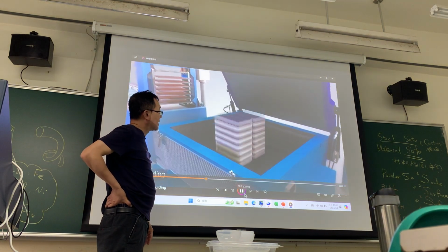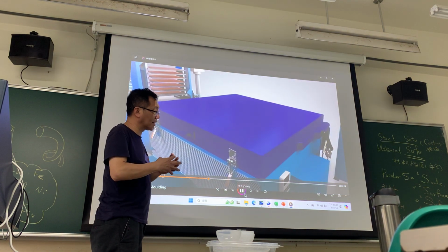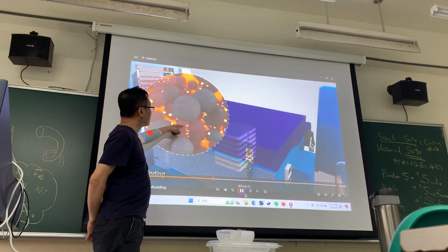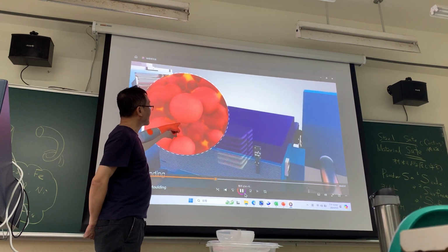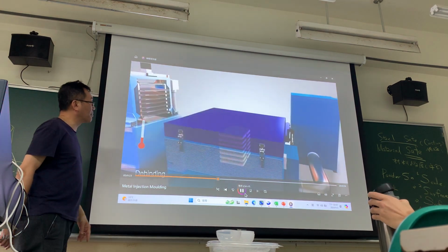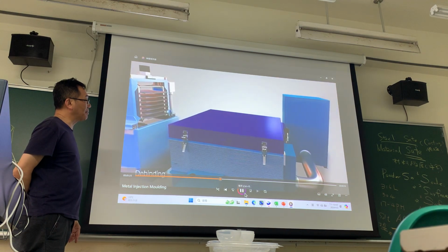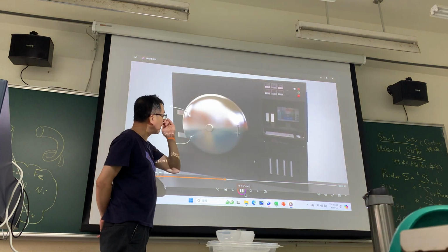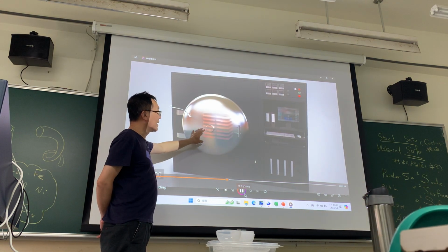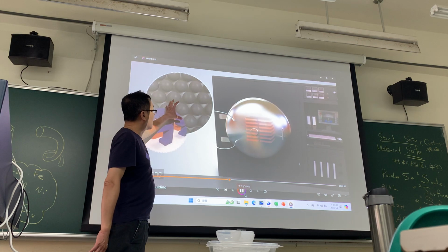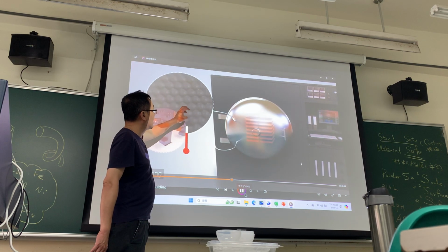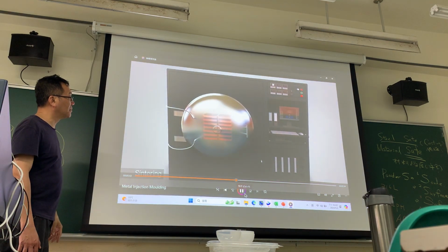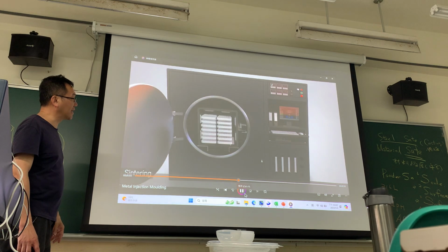Okay, this is baking, then let the green part go back to its original shape. Just baking and removing some binders, and it becomes brown, so we call it the brown part. Then the brown part goes into the sintering furnace. This one is a batch type furnace. Use the vacuum and the high temperature. Then the powder will close and close more, and sinter together to become a solid material. This one is a silver part.